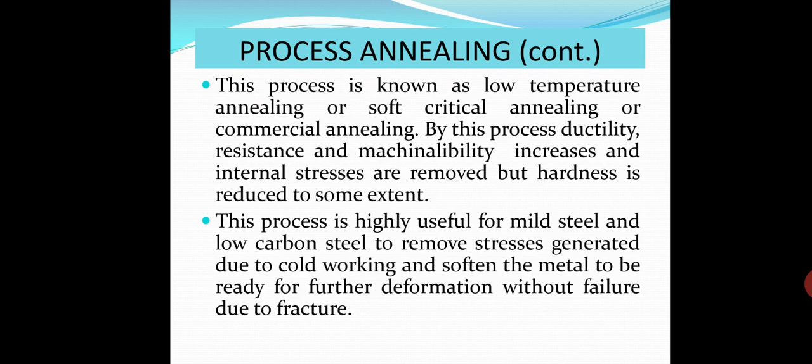This process is known as low temperature annealing or sub-critical annealing or commercial annealing. So the temperature raised is below the lower critical point. By this process, ductility, toughness and machinability increase and internal stresses are removed, but hardness is reduced to some extent.